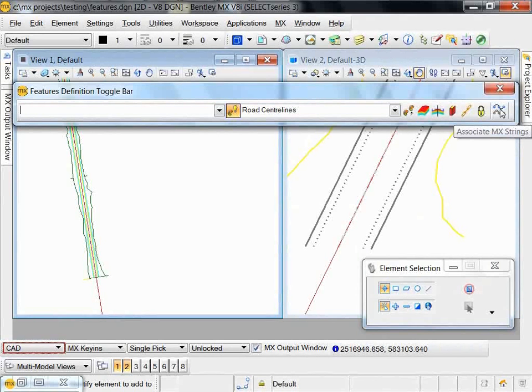This allows us to take the geometry that we're producing and project the stroking from a reference element onto its children elements. This happens automatically in the MX environment, but because we can define everything as geometry, we may need to project the stroking from one feature onto another to preserve the point indexing that we'd normally be familiar with